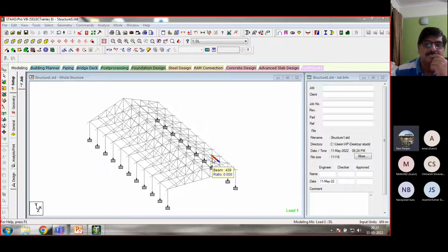And for roofs like a bus stand shade, petrol pump shed or a stadium shed, the shapes are different, like a top shape or any different type of shape. If the stadium cover is in an arc shape, first we have to create that arc shape in AutoCAD, then import it in StaadPro and analyze it by giving properties and loads on it.